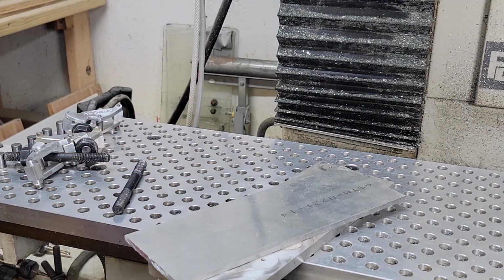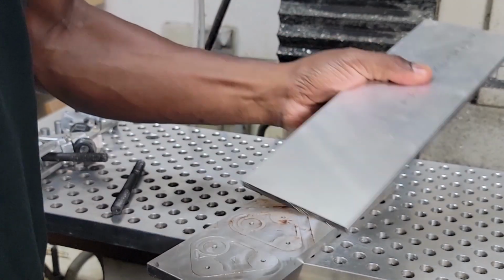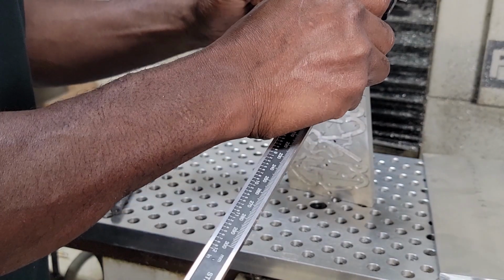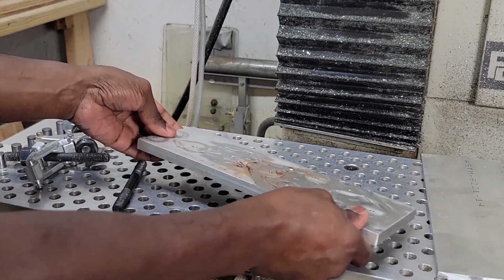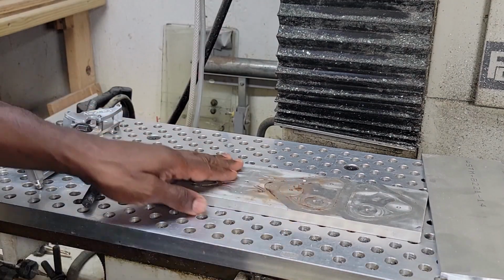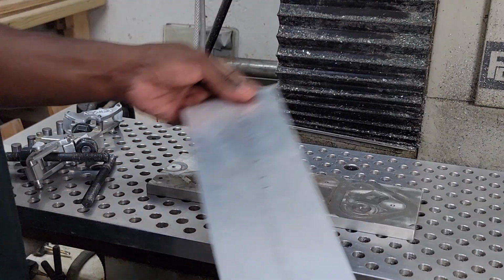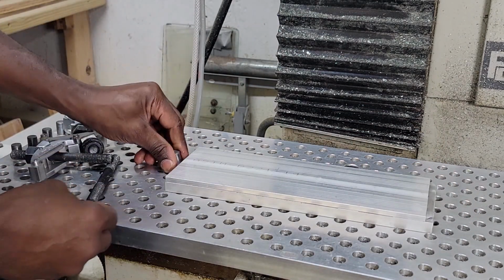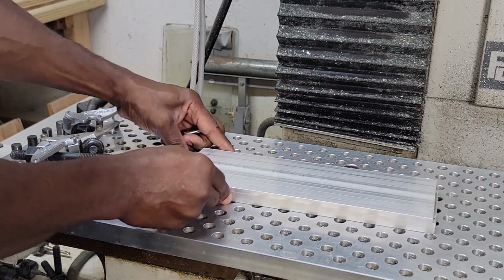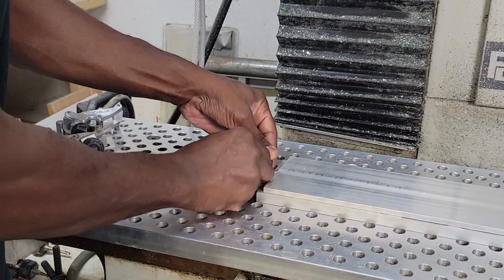So this is my quarter-inch workpiece, and the aluminum is about a half an inch. So what I'm going to do is set the half-inch thick aluminum down, and this workpiece is going to go on top of it. And first I'm going to use some dowel pins just for location, to help set the location.